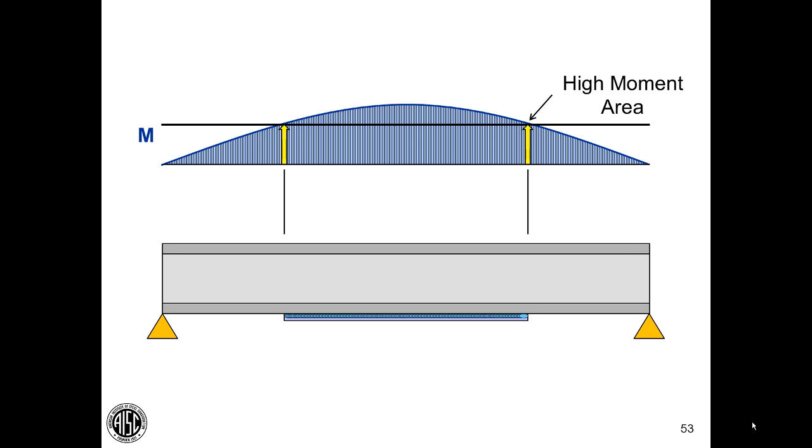But I want you to notice the end of that cover plate. And assuming I have a fatigue-sensitive application where I need to consider the fatigue categories and the stress range, I want you to see that this cover plate terminates in a high moment area. And that cover plate is designated either a category E or E prime detail.